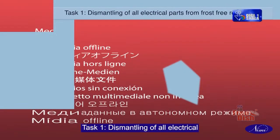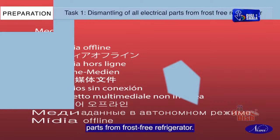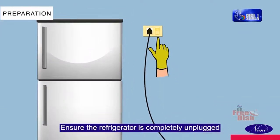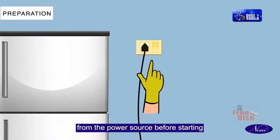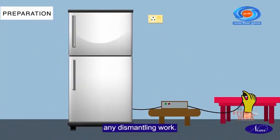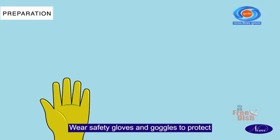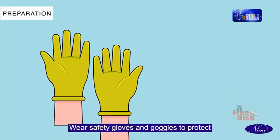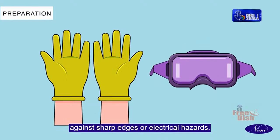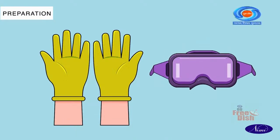Task 1. Dismantling of all electrical parts from the frost-free refrigerator. Ensure the refrigerator is completely unplugged from the power source before starting any dismantling work. Wear safety gloves and goggles to protect against sharp edges or electrical hazards.